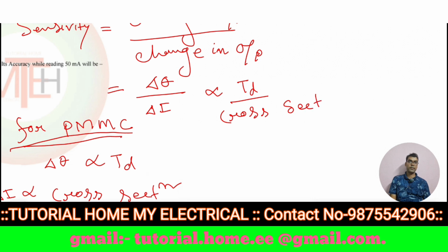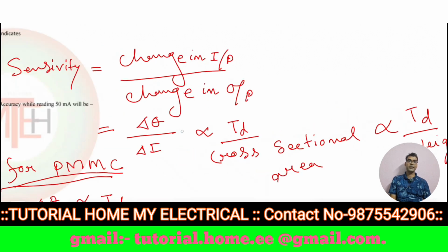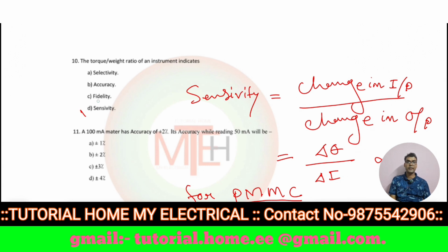If cross-sectional area is also proportional to the weight, then the sensitivity is proportional to the torque and weight ratio. So the answer is sensitivity. We prove here that sensitivity is proportional to torque weight ratio. Now going to the next question.